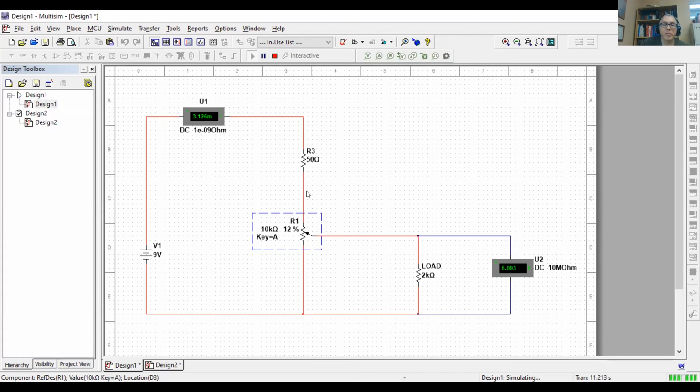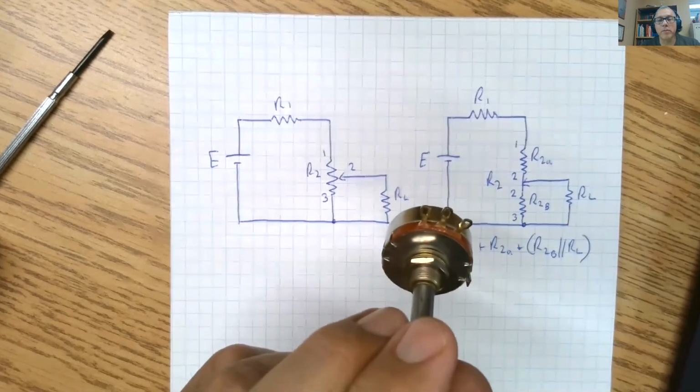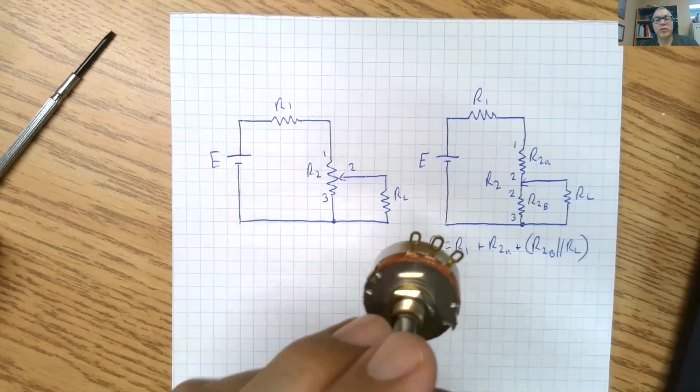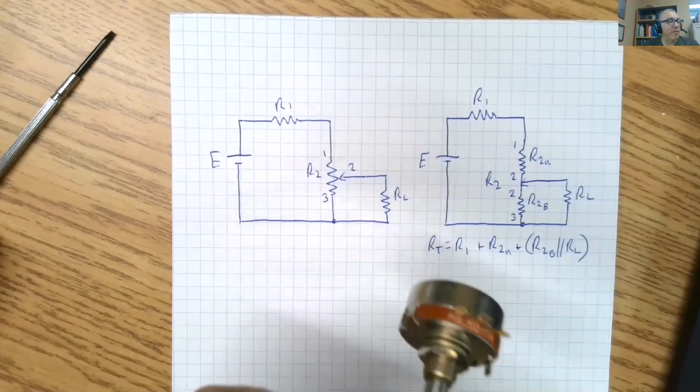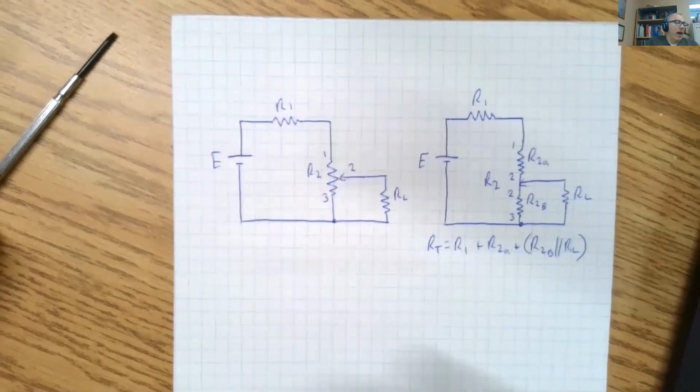Okay, so this is when a variable resistor is used as a potentiometer, which in turn is used as a voltage divider. Okay, so you're going to hear those two terms used a lot over the next few years: potentiometer and rheostat. Okay, you're also going to see these referred to directly as a potentiometer. So when you see these in catalogs or magazines, you'll see this a lot of times called a potentiometer. All right, but this can be configured as a potentiometer and as a rheostat. It's important to know the difference, how they're used, when they're used.